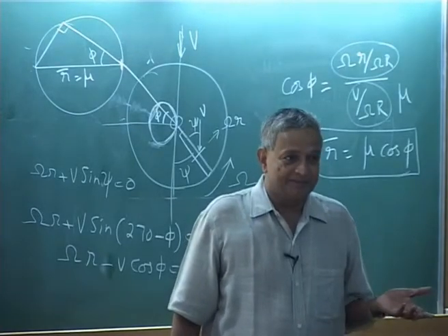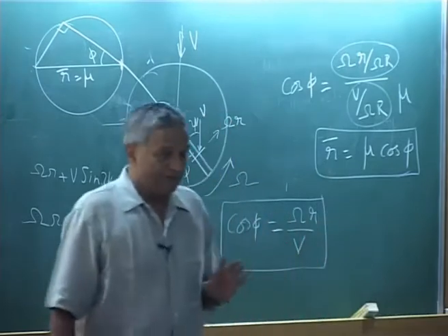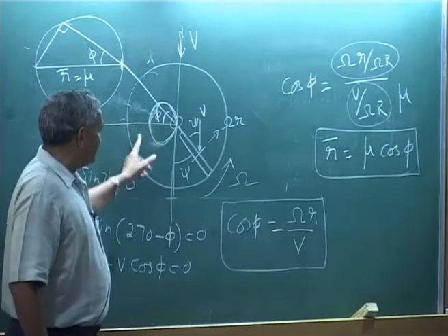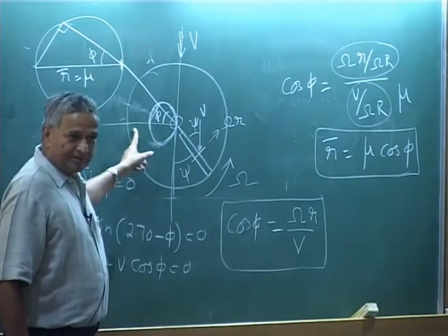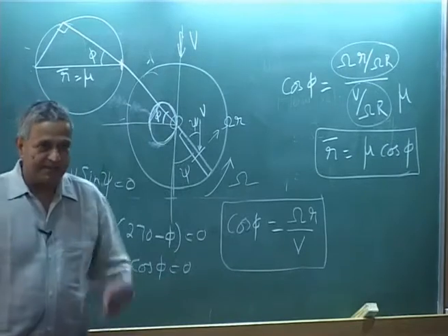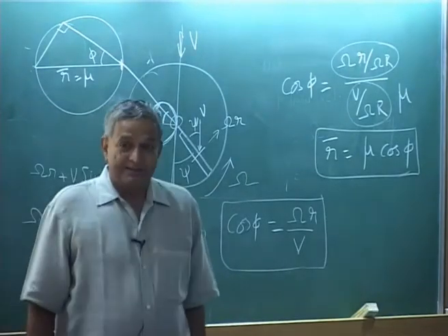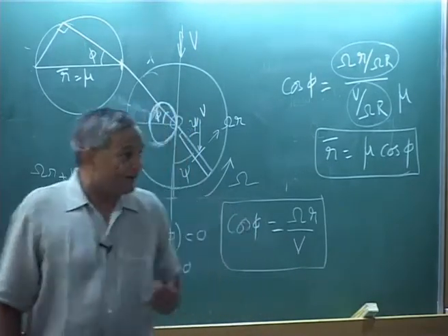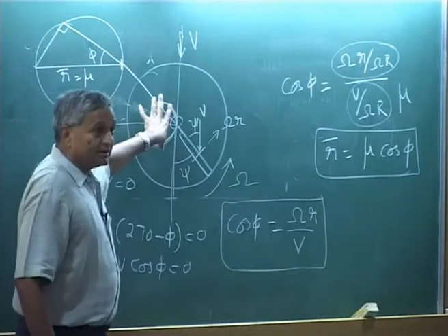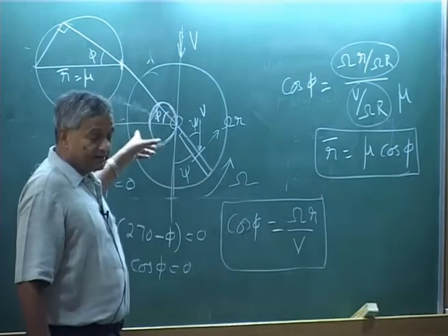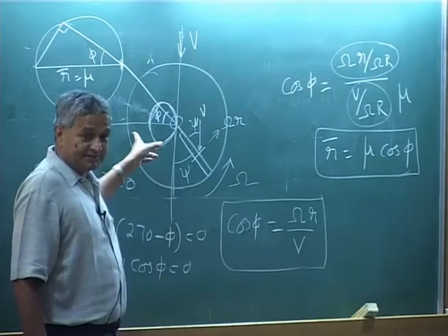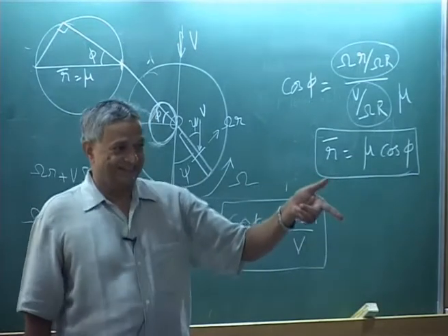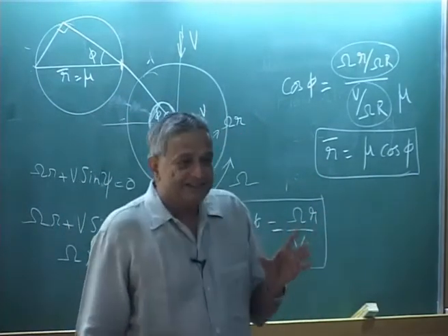not generate lift. Okay. Because please remember, the flow is highly complex. In this zone the flow is coming like this, here it is coming like this. Okay. The net relative flow, net air velocity. So, you have stall problem, you have reverse flow problem. So, what will happen is, if this region becomes bigger and bigger, you need to generate lift here, which means you have to increase the pitch angle. That means, if you keep on increasing the pitch angle, you may stall. So, you see these are restrictions.